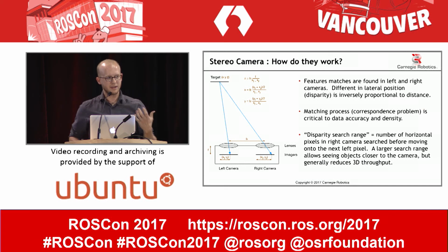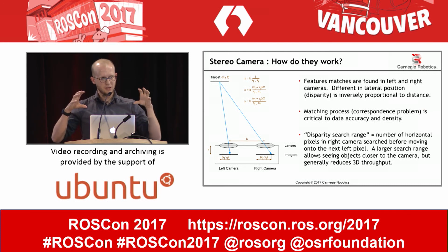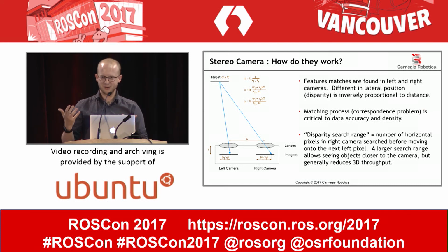And if you have a very accurate model of the distortion of your camera lens and a very good understanding of the particular arrangement of the two lenses, their distances and their mounting angles, you can relatively accurately construct the 3D scene that the cameras are looking at.